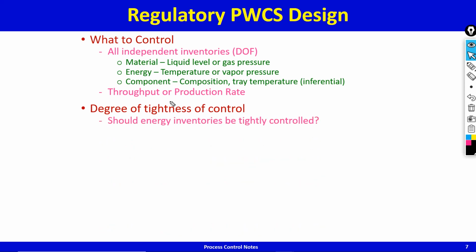So should energy inventories be tightly controlled? Usually yes, because energy inventories typically in reactors have a way, reactor runaway can happen if temperature starts to rise too much. Okay, so you need tight control of the energy inventory in a reactor. So typically energy inventories are tightly controlled.